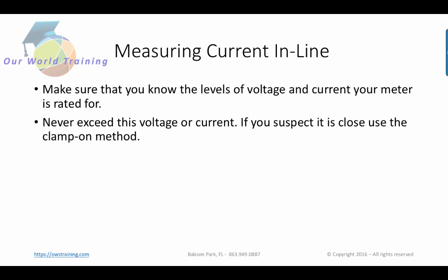Make sure you know the levels of voltage and current your meter is rated for. This is why I said ask the directions. Don't exceed it. If you suspect it's close, use the clamp-on method. Meters cannot handle a lot of amperage going directly through them.